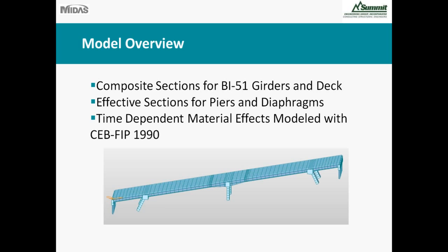The reason we did this was because the post-cracking behavior of the piers allowed them to be a little bit more flexible, and the bent caps were experiencing high degrees of compatibility torsion, which did not affect the equilibrium of the structure, however, attracted a lot of torsion with any kind of differential loading. So I did some research and was able to reduce the torsional constant of these sections, allowing for more efficient reinforcement just based on the true behavior of the structure.